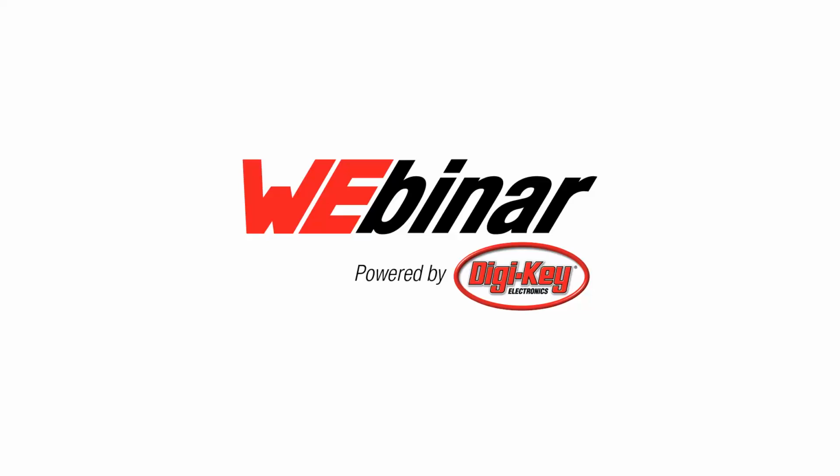Another question: are you going to have this type of technology in 2mm or less? We have it right now in 2.54, so I'm not sure if 2.54 is sufficient or it has to be 2mm. On the other side, having it in less than 2mm is going to be tough because of the creepage and clearance and the UL standard.